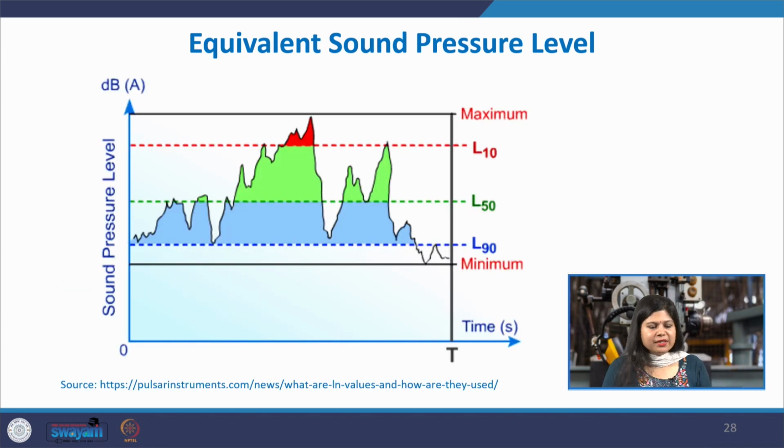This shows a typical sound pressure level distribution. Here L90 corresponds to the background. This was the overall background, and then in the middle whenever there were nearby sources, the level increased. Otherwise, when no nearby sources were present, this was the level that was maintained, this L90 over here. Then L50 and L10 are some of the common measures which correspond to more acoustically intensive events.